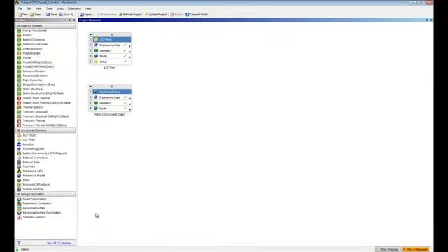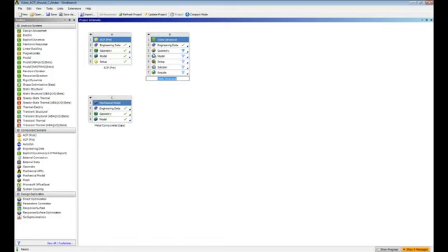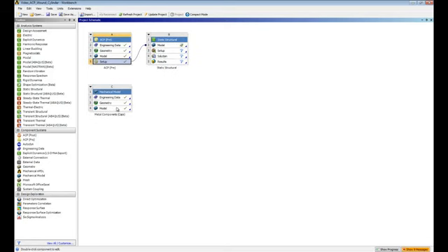So now we have all of our models, both the composites and the non-composite parts, that we are going to assemble to create a static structural analysis of it. So basically we create a static analysis, take the setup from the composites definition, take the setup from the non-composites parts, and we are going to update the system so as to assemble both parts together.